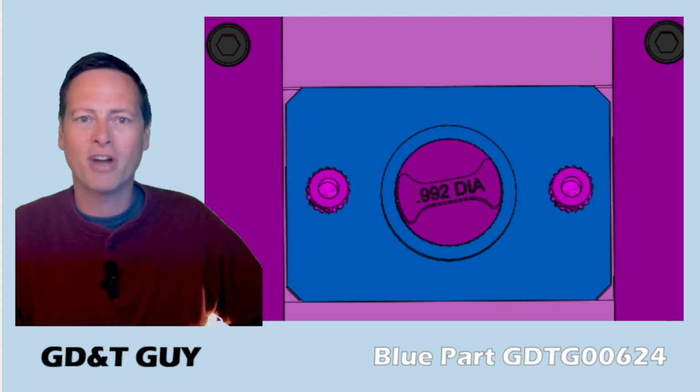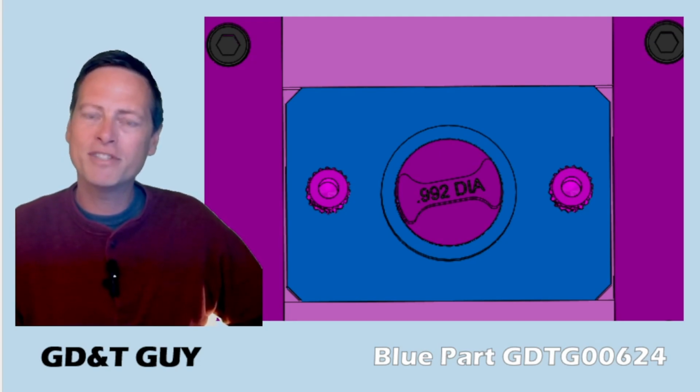Pushing up against the dark purple edges here. And if we were close to the least material condition on the 2-inch wide datum B feature, so the most clearance possible with the datum B simulator, which feature would be orienting the part in that case? Which is the 1-DOF datum reference and which is the 2-DOF?